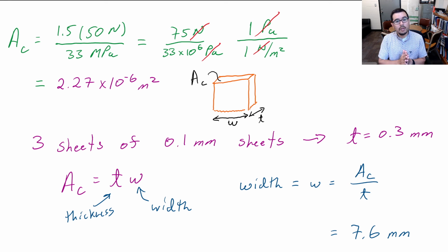Now, one thing you want to make sure you do when you're calculating the appropriate thickness and width is take a look at the sample that you're given, or the multiple sheets of paper, and their cross-sectional area. Make sure that you can get the thickness that you want. Make sure that you can get the width that you want. These samples, we can cut them down, but it's very hard to add material to make them wider. So as you're designing and calculating the appropriate dimensions, the cross-sectional area, the width, the thickness for your sample that's going to be under load, keep these factors in mind.